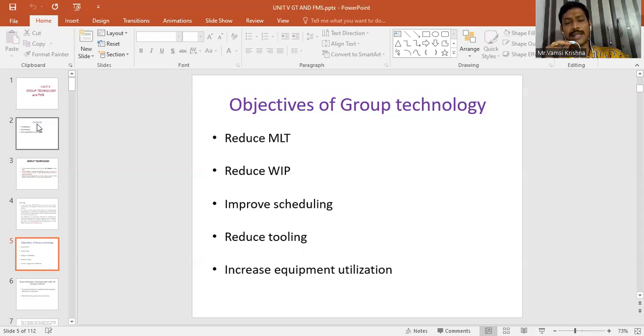And let us say in the second workstation, the machining is done within 5 minutes. So there is a lag of another 5 minutes, 10 minus 5, where the second workstation has to be idle for 5 minutes.